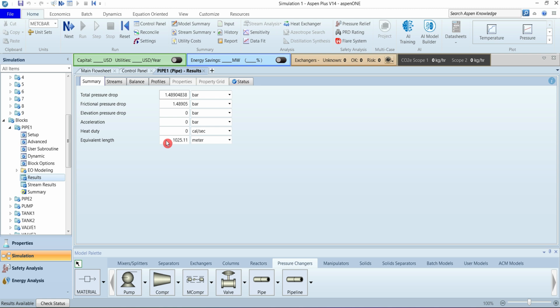Here you can also notice whether this pressure drop is appropriate for this pipe segment or not. Generally, in a pipe delivering liquid water, the maximum allowable pressure drop that is used for the line sizing is around 1.5 bar per kilometer. So that means we are pretty much close to the actual pressure drop that is allowable for any pipe network.